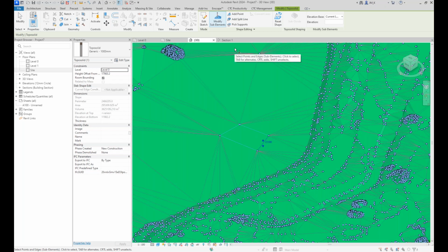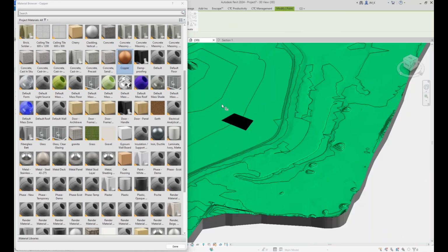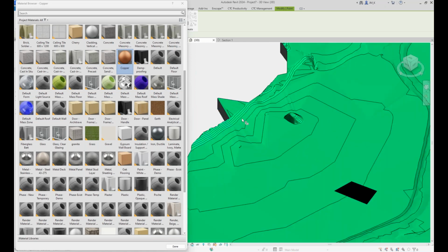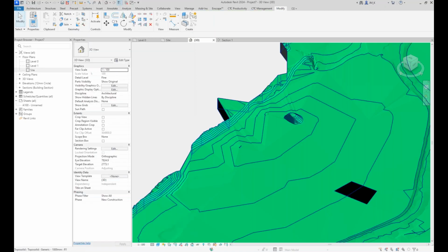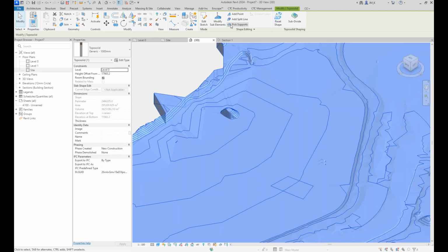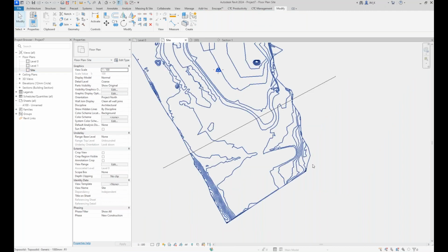But the idea is that inside those split lines, you can actually use the paint tool. I don't know if it's going to let me do this, but let's just try it. There you go. So I can use the paint tool. It's a bit of a funny one too, because you can actually use the paint tool on these faces. It's a bit unpredictable though. So anyway, you can do that in the same way that you can on 3D objects in Revit. Okay, so that's that. You can also split this, and this is something that you do right at the very, very start.